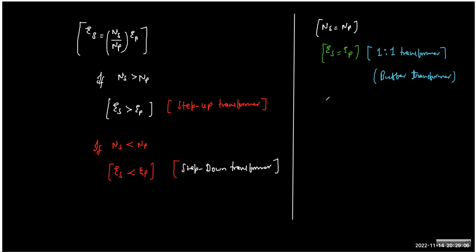Now, what is interesting is that a high voltage will make sure that you will get high current, yes or no? Yes. And ironically, the answer is no. High voltage doesn't mean high current. You know why? Because that is a violation of conservation of energy. If primary is giving you 100 joule per second, can you produce more than 100 joule in secondary?